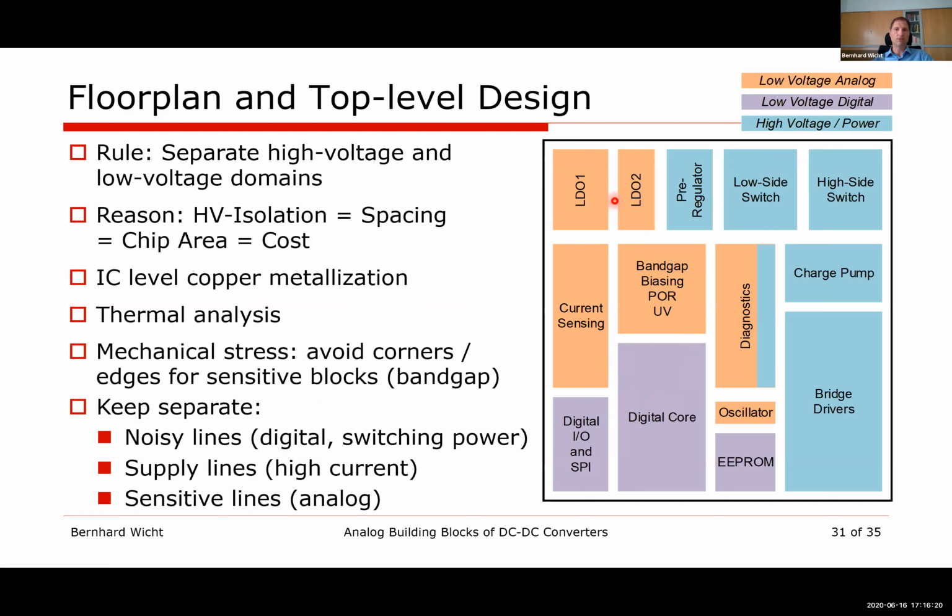I've seen it myself that you easily get 10 millivolts, 20 millivolts of shift in bandgap references. So we don't want to place these blocks at the periphery of the chip. And of course, it's self-understood, we need to keep the noisy lines and high current supply lines away from sensitive analog signals, as in any other design.